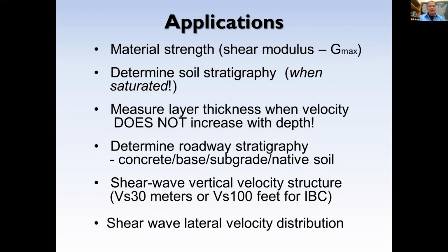Soil stratigraphy, and I think this helps particularly when you have saturated soils. The layers don't have to increase with depth. You can find those hidden layers in the inversion algorithms that are set up for them. And I've also seen it used on roadways and tarmacs and things where the stiffest layer is right at the surface, and you can see beneath that stiff layer. And the shear wave velocity for the IBC site class, VS100, as it's called.